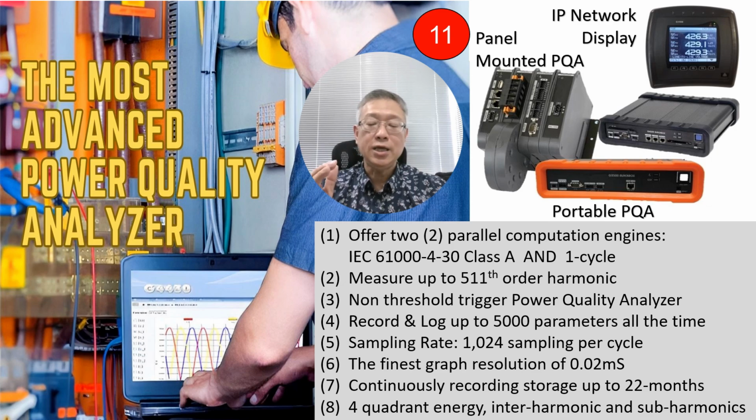This power quality analyzer can offer two parallel computation engines. One is fully compliant with IEC 61000-4-30 Class A, and on the other hand, it also goes beyond IEC with single cycle aggregations. So it measures harmonics up to 511. No need for thresholds to be set.